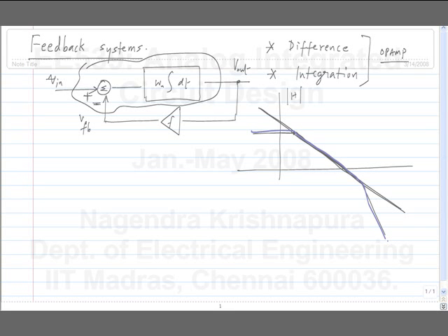So, how would we go about doing it? Now, we know how to make amplifiers, and if you look at most of our amplifiers, they take a voltage in and give a voltage output, but what is happening internally is that they convert the voltage to current, and that current is in turn converted to a voltage using a load resistor. That's how we have the common source amplifier, for instance.